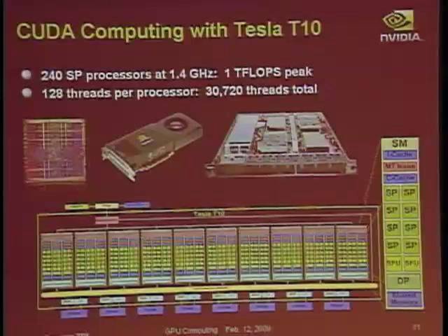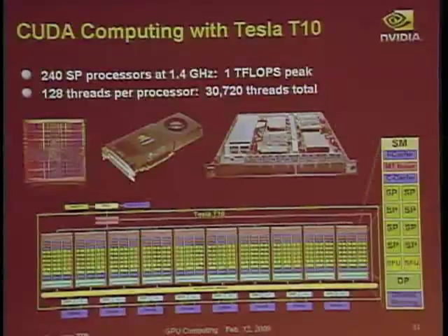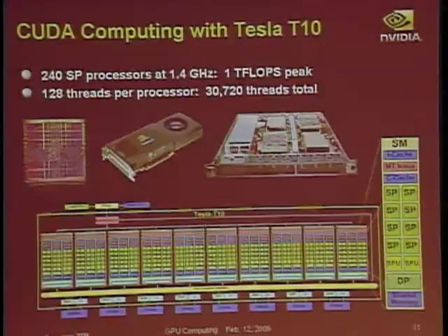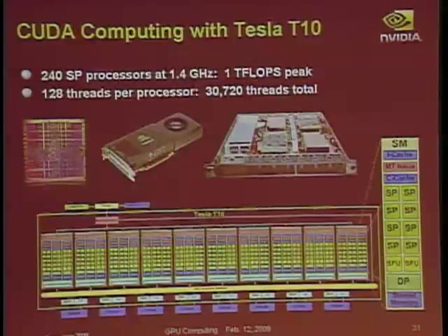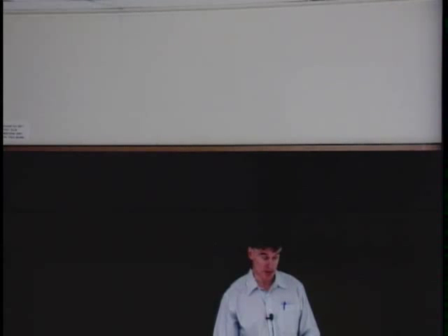So, we pick a pipeline stage count that we think we can implement that doesn't break the budget. If you take too many pipeline stages to do something, it's hard to get it to fit in with the rest of the processor. So, the way the approximations are done is they do table lookups to get initial seed values, and then they interpolate between adjacent table locations. So there's a linear interpolation going on in there.